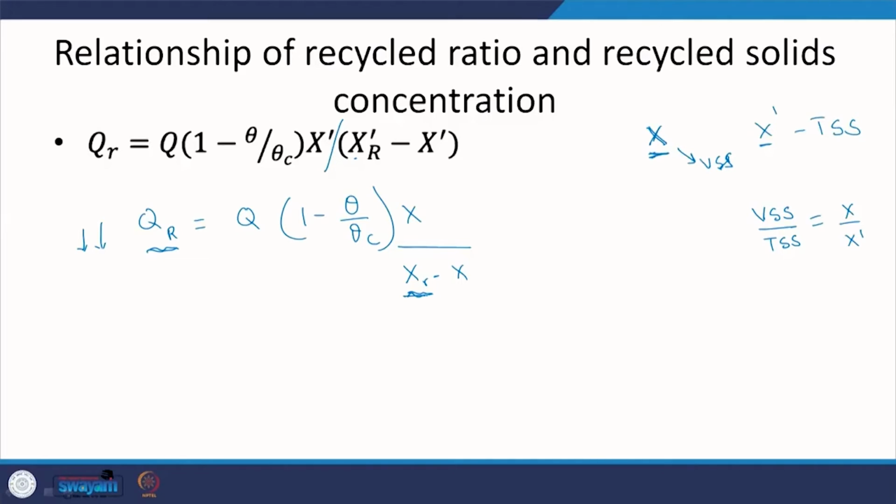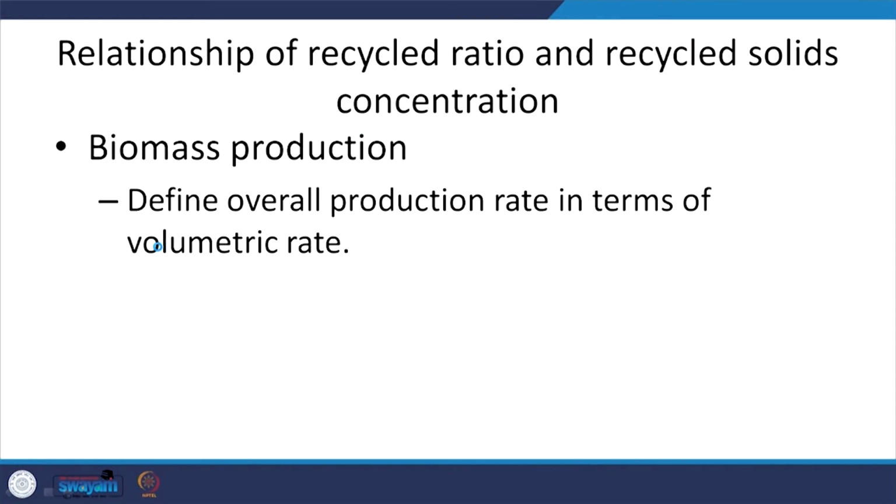We are always concerned about the mass, right. But if the sludge is not settling well, obviously I have to pump more of the relevant sludge. So, that is something to keep in mind. In those cases, we are going to have issues with steady state and such, but that is one aspect to keep in mind: XR and QR have a close relationship. Let us move on and look at what else we have.